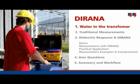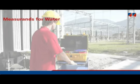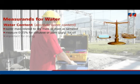Now to take a closer look at water. Where is it in a transformer? First, it is necessary to discriminate between two measurements used for water. One is water content. Content refers to the relationship between the water mass to insulation mass.